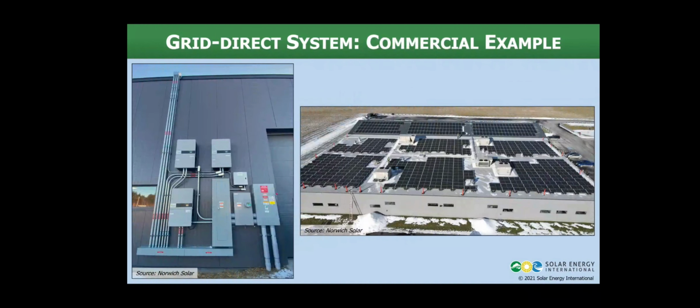Commercial grid direct systems are also very common and are essentially just larger versions of residential grid direct systems. They tend to have more components, more complexity, larger size, but the concept is the same. There will be two sources, the PV array and the grid. In this case, we can see the array on the roof of this building, and then coming off of the roof in large conduits to 3 inverters. On the left, you can see we have our inverters going into an AC combining panel, which is right in the middle, and then that goes into a meter and then to a system disconnect.